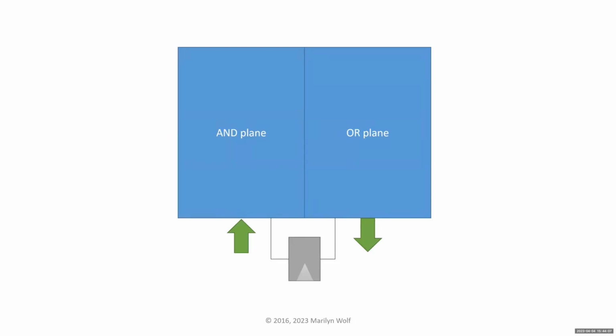So the PLA is organized into an AND plane and an OR plane. There are actually inverters on both sides, but those are relatively small. Okay, so we put inputs into the AND plane. Those values are then sent over to the OR plane, and then possibly inverted on the outside, and that will give us the AND or not functions that we need for a complete set of Boolean logic. One of the nice things about a PLA is that we can also add a register between some of these inputs and outputs and create a state machine.